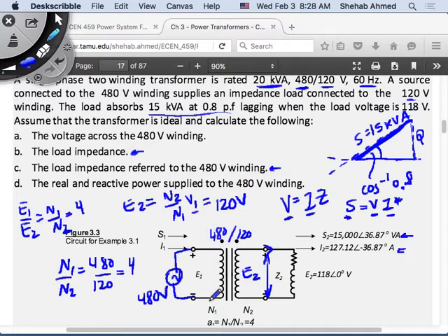Assuming now I don't know that this box has a transformer. This is a box. This box is consuming current. I'm putting a voltage and it consumes current. What does that mean? It means that there's a load connected, right? So I can sort of figure out a way to, and this load, if I don't know it's a transformer, I can assume it's nothing but I know it's a, I will see a lagging power factor. So I will say, okay, it's a RL load.